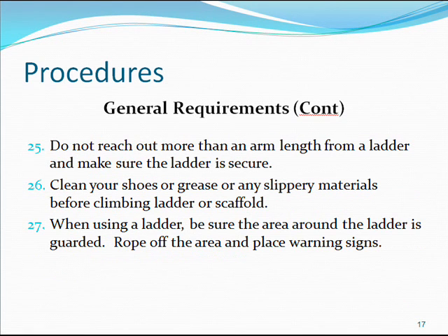Do not reach out more than an arm's length from the ladder, and make sure the ladder is secure. Clean your shoes of grease or any slippery materials before climbing a ladder or scaffold. When using a ladder, be sure the area around the ladder is guarded. Rope off the area and place warning signs.